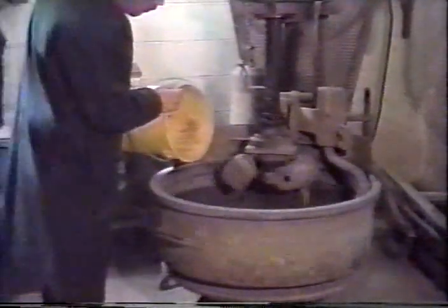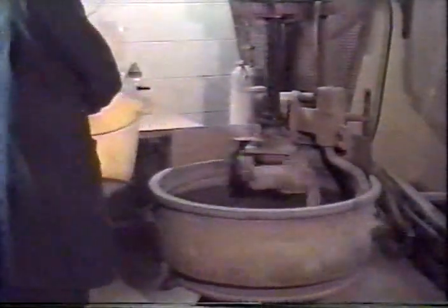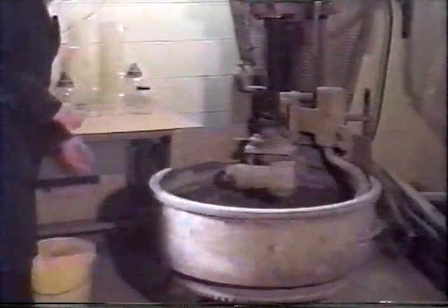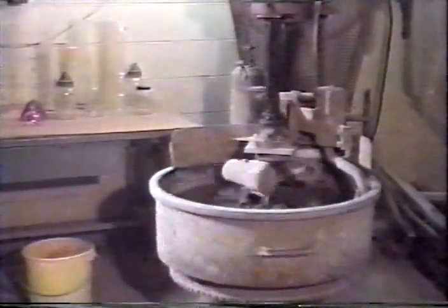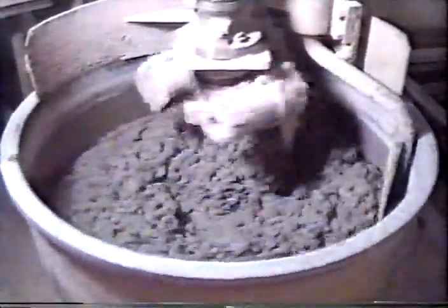A mix-specific strength-velocity relationship is developed prior to construction using concrete that contains the same materials, aggregates, cement, and admixtures that will be used in the job mix. The use of different material sources and quantities generally affects strength-velocity relationships and results in significant strength estimation errors.